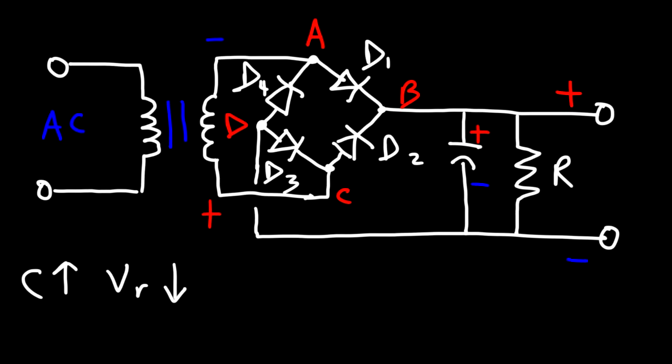So once you apply the AC signal to this rectifier, and if the capacitor is fully discharged, which it's probably going to be in that state, instead of current flowing through the device that's connected to this rectifier or even through the resistor, it's easier for current to flow through the capacitor because the capacitor will be charging.